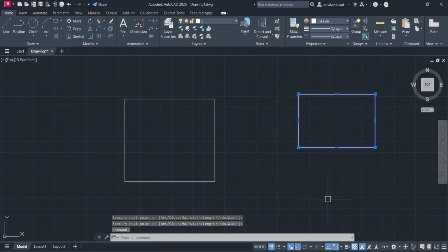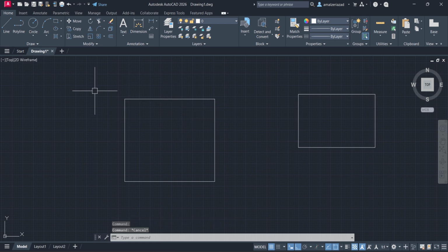Okay, suppose I don't want it like this. I want a particular line to be selected. At that time, you directly go and click on this explode, choose this, and press enter. You can see now each and every line got separated, right? That is how it is. If you go for the explode, each and every line will be getting segmented.